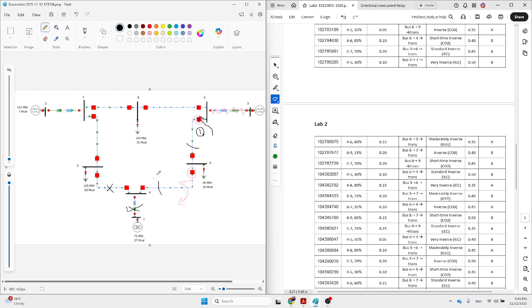Based on the regulatory, it is a bit different. So again, for the next person whose fault is by here, you should go back to the transformer. So this is the relay, then again this one, correct? I think I did this one. Oh, sorry. For whom the fault is at this point, meaning 6 to 9 or 9 to 6, no problem. This is the first closest, and then this relay. So this is the distance relay you must choose and make the coordination.